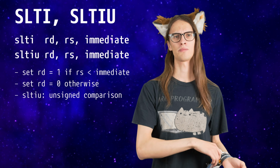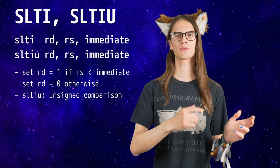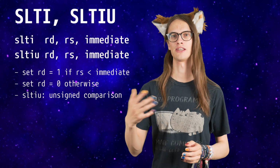I had some trouble deciding what to do with those 2. Set less than immediate is intuitive in what it does, but a bit mysterious in its purpose if you ask me. It compares the register operand to the immediate and sets the result to 1 if the register was less than the immediate and 0 otherwise. Same thing with unsigned comparison in SLTIU, of course.